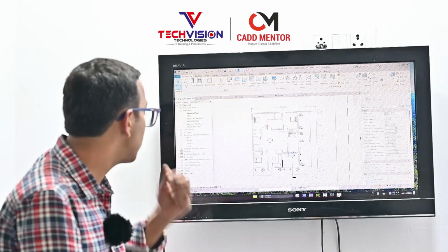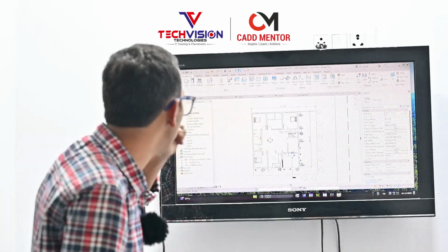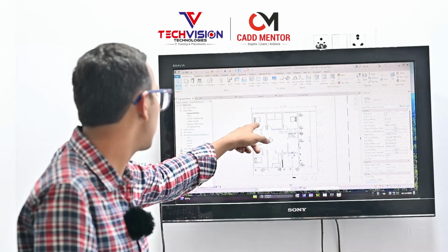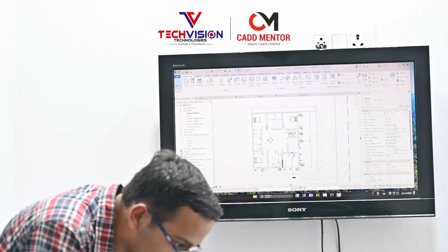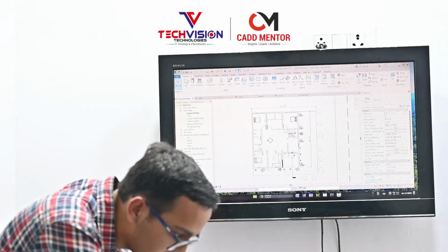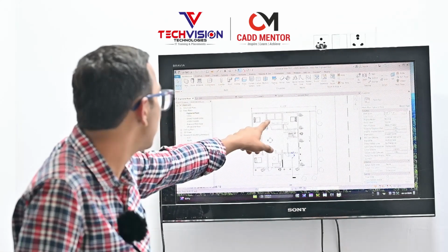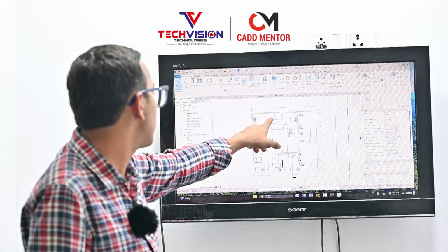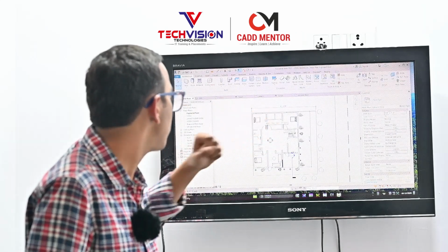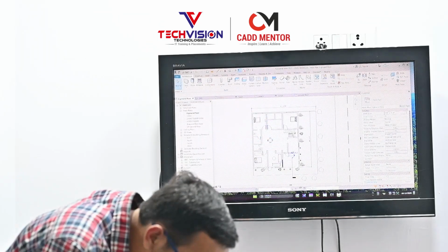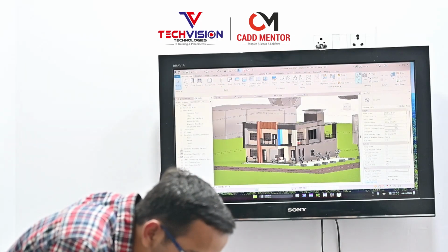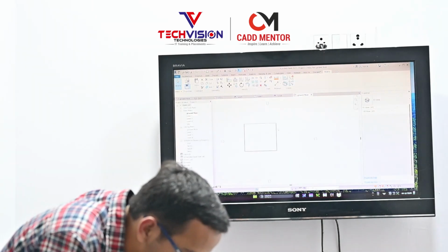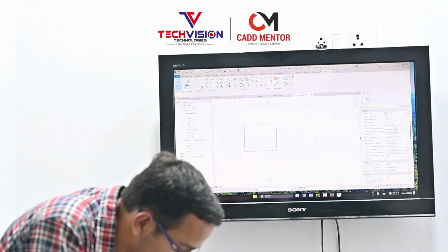So here you can see this is the bedroom. We have shown the first bedroom, then second, and third bedrooms here in the plan. So after all, you can see these outer walls are 9 inches walls, and the partition wall should be 4.5 inches compared to the external walls. So after all this is the full plan, and after we should give it another object. So offset.